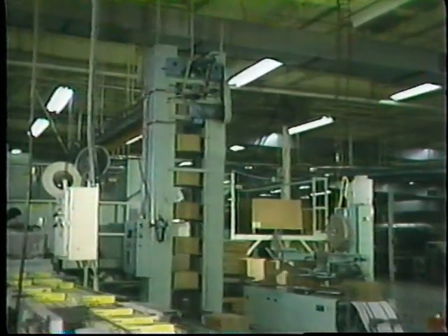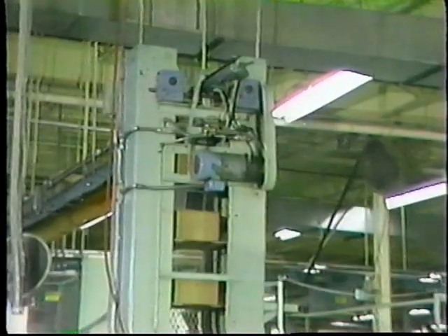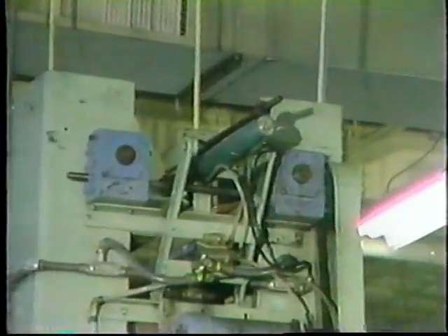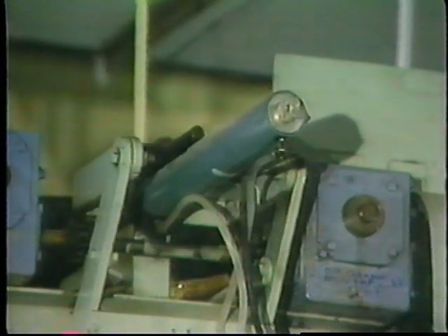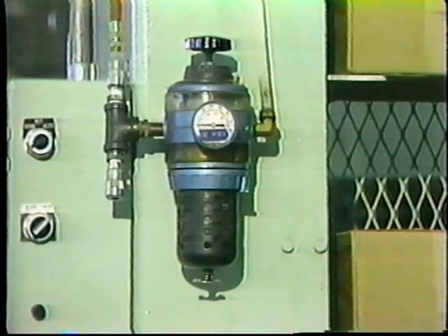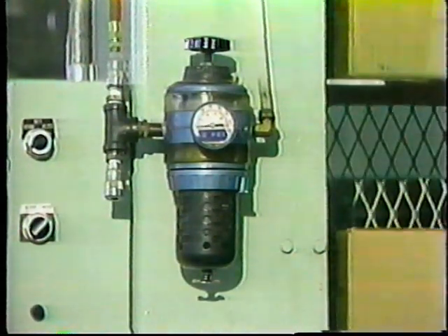The valve will maintain constant airflow only if the resistance the actuator encounters, and that's the total load consisting of friction and the load itself, are constant, and the pressure both at the inlet and the outlet of the cylinder do not vary during the entire work cycle. So in actual fact, the needle valve does not control flow. It really only affects flow.